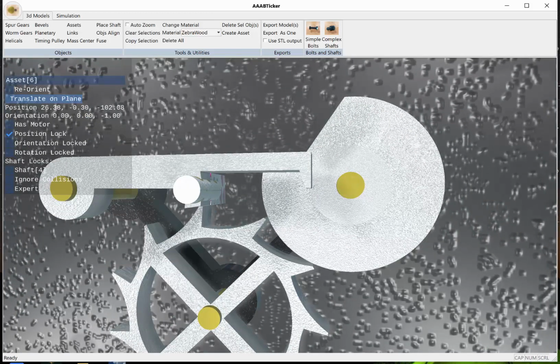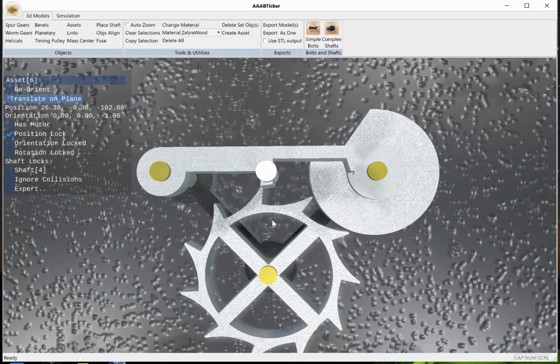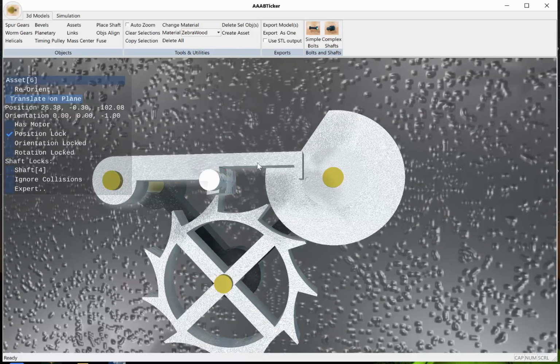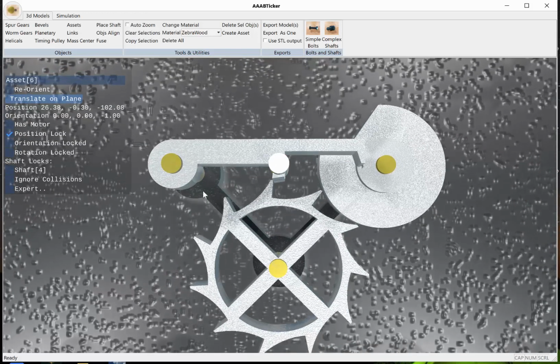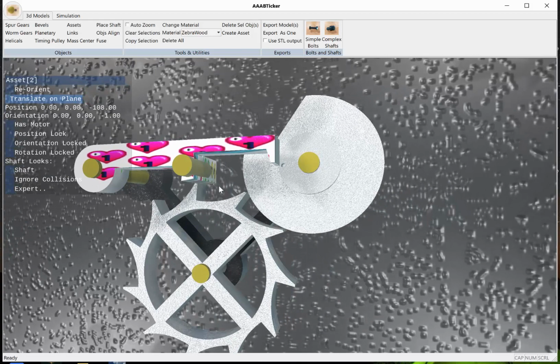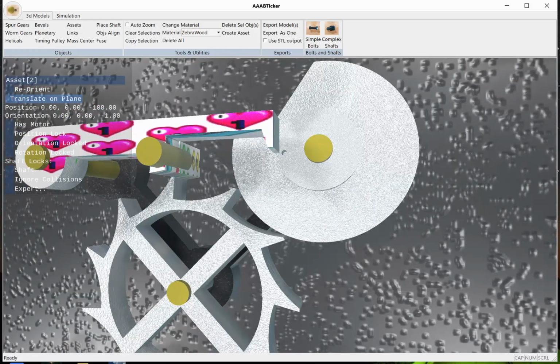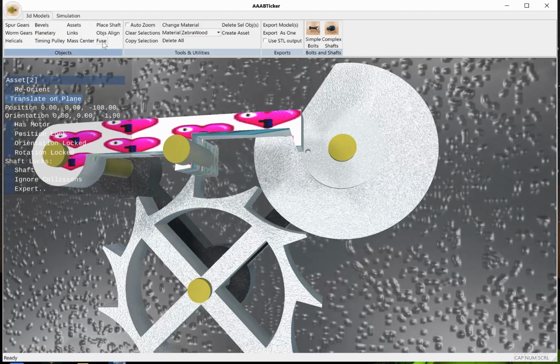But now we have a problem. If we were to move, any torque on that would spin it, and I really don't want it to spin. I want it to be solid. So I'm going to click that. I'm going to click master first. Most commands in the program, no matter what you're doing, go by master and slave. So on this, the arm, put this, and I'll select the block as my second piece. So as you can see, the block has the number 2 on it. The master has the number 1, and I'm going to hit the fuse button.